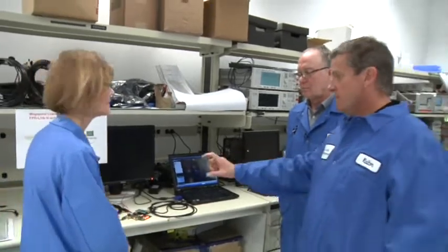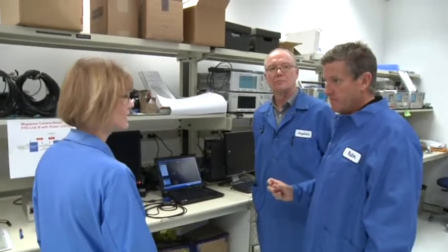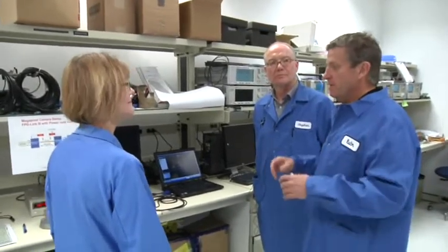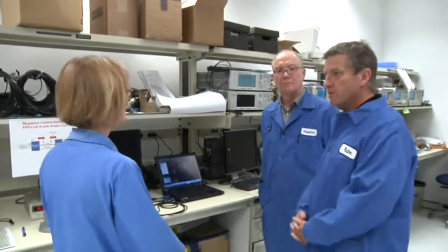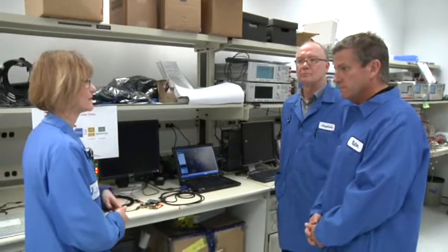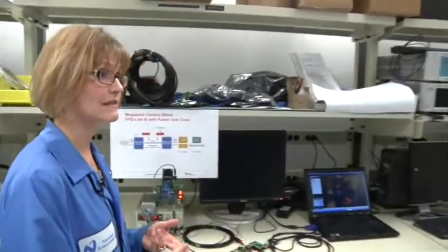So what are your design challenges here? You know, we talk about the automotive environment, okay? A lot of vibration, a lot of noise, heat, cold. Right, so certainly the extended temperature range that's required for automotive products, so the minus 40 to 105 degrees C, so that's standard automotive AEC-Q100. The ESD protection that's required for automotive, so that's all built in, so these devices support the ISO and the IEC requirements for automotive grade ESD.